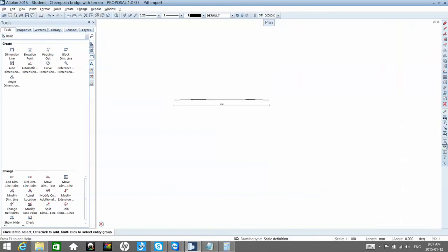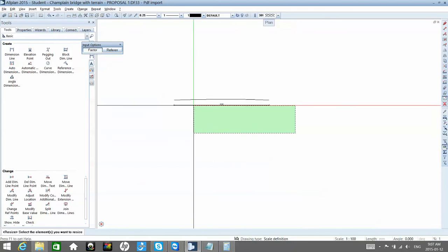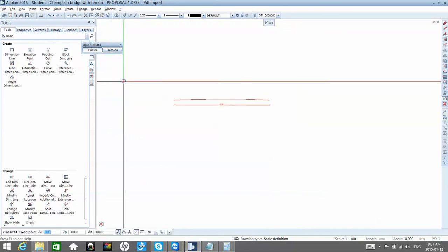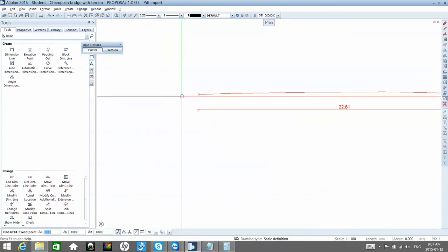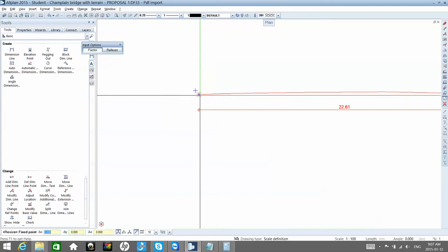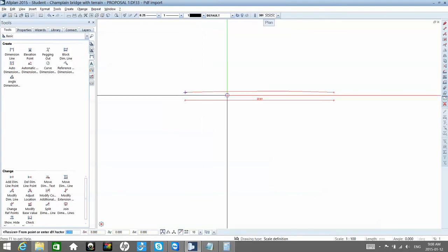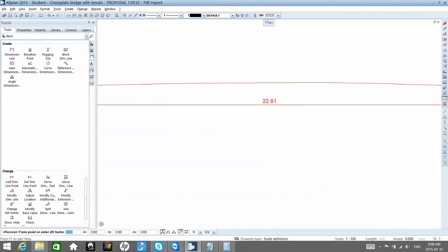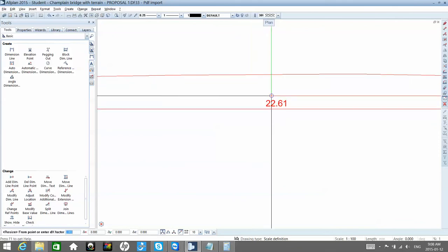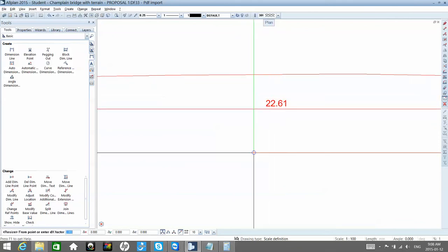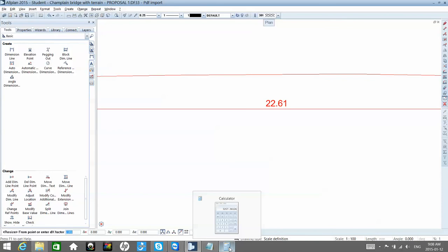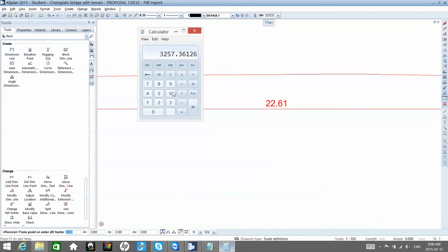Okay, and now I'm going for this function called resize. I'm going to select this, pick up the origin, which is the start of this elevation. And now we're going to give some factors for x, y, and z. There's only going to be a factor for x, as on y we want those dimensions. Hopefully they're correct.